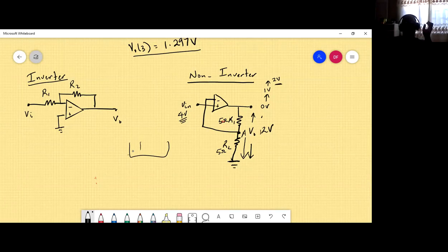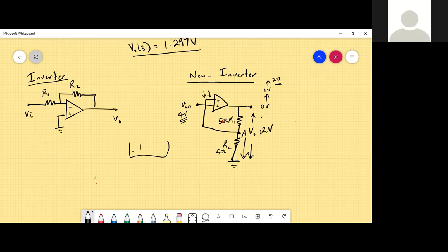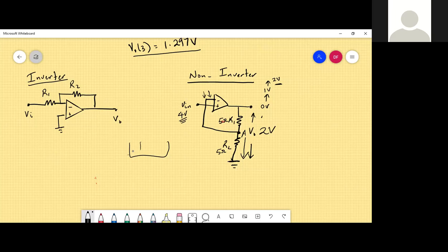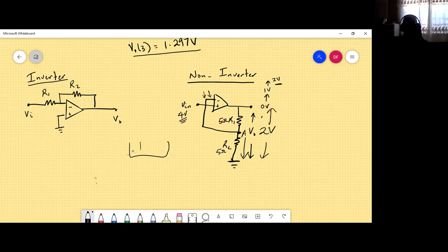What would the voltage at the non-inverting terminal be? If this is 2 volts, if the voltage across the output is 2 volts. Sir, you say right at the junction between the 2 resistors, because at first you have 10 volts, so you share it in half, so you have 5 there. So what's the output, which is 2? No, that'd be 6.